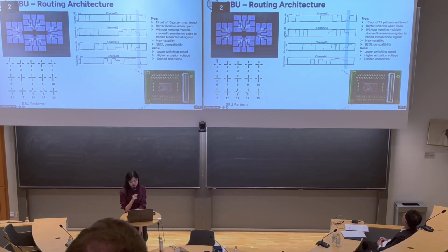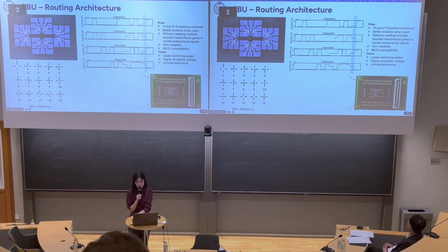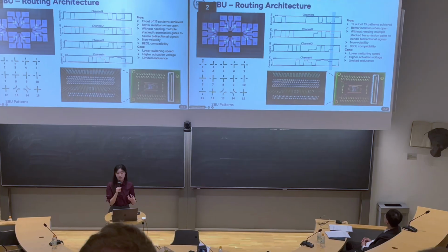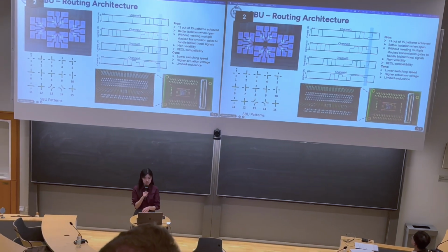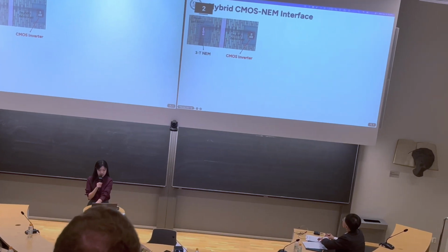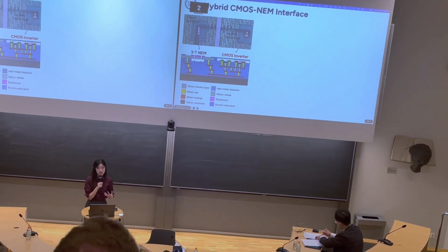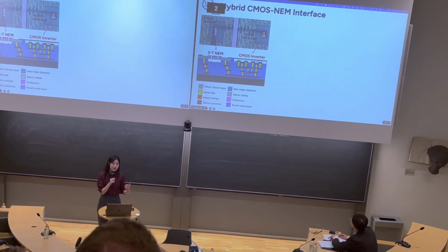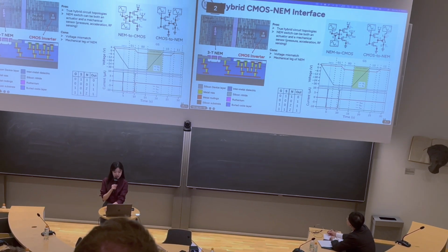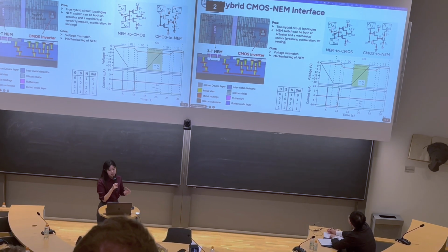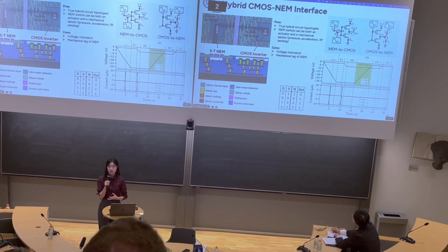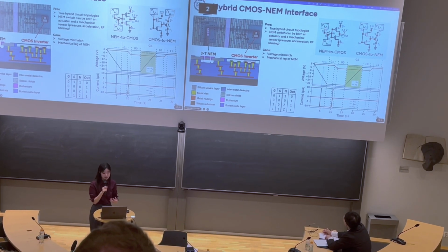After the initial test on the chip level, we also do the wire bonding on the devices for the following packaging and integration demonstrations. So finally, we have these NEM and CMOS transistors integrated together next to each other on the 3D integration platform. And this tool has been interfaced in both directions, so we can have both CMOS-driven NEMs, and we can also have the NEM-driven CMOS.